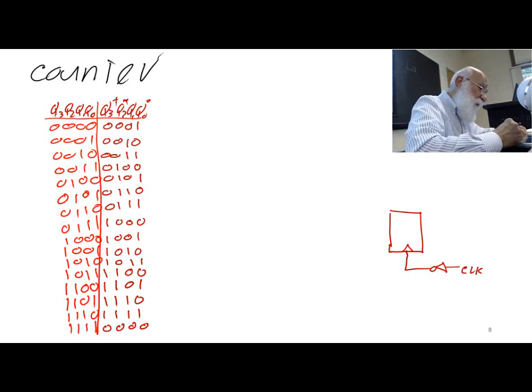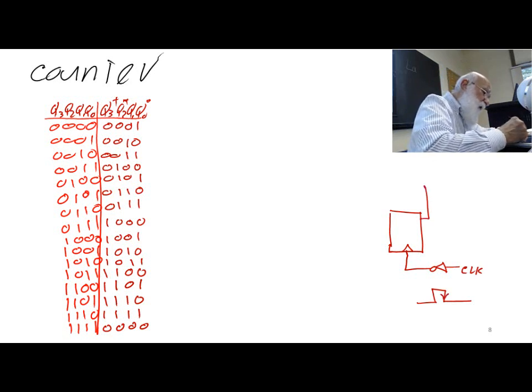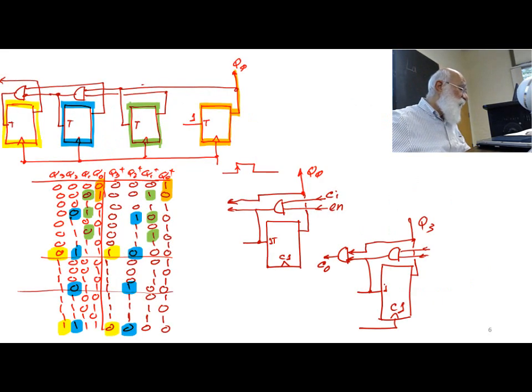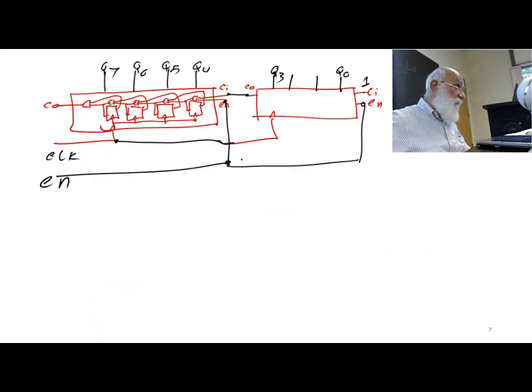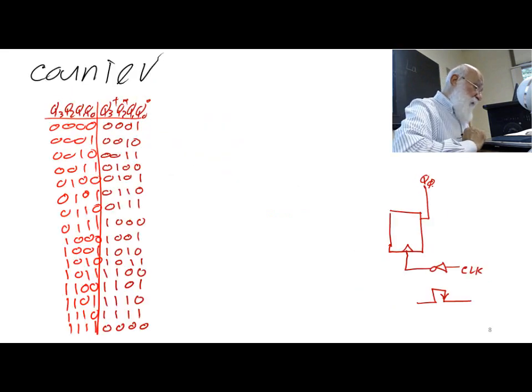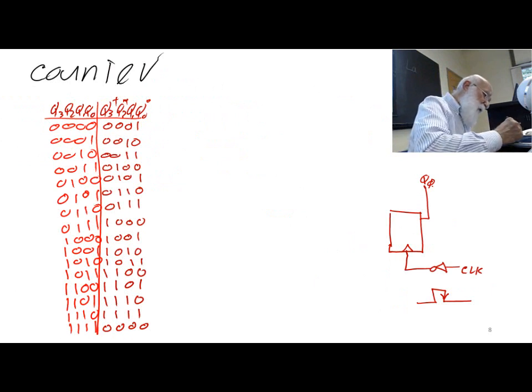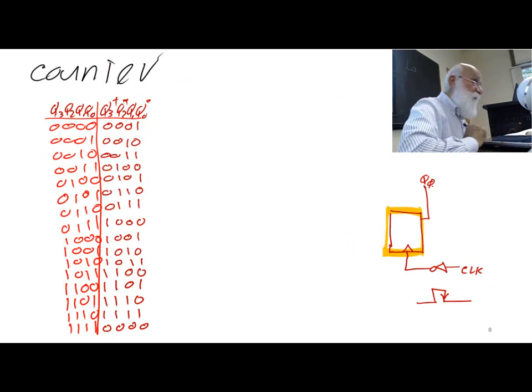What it means is, unlike the previous one, when the clock goes from 1 to 0, this toggles, and I'm claiming this is the Q0 output, which it is. Not very different from the structure I have here. So anytime clock goes from 1 to 0, this one toggles, and therefore this is indeed bit number 0 of my counter.